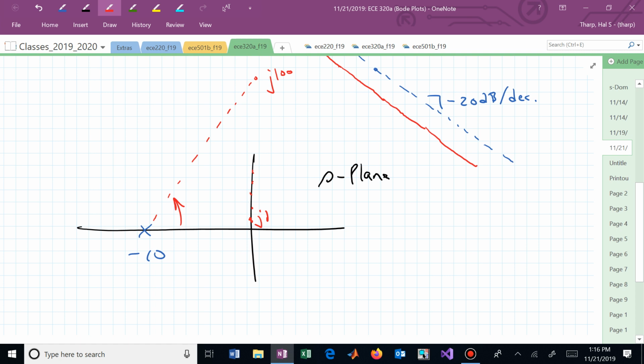90. We can only go to infinity, and we can only obtain a right triangle. So now that one pole factor only contributes 0 to 90 degrees of angle. And since it's in the denominator, we'll actually be subtracting these contributions. And what have we done? We've played Goldilocks again. We said, what's small? Oh, it's a decade before the break. What's big? A decade after the break.